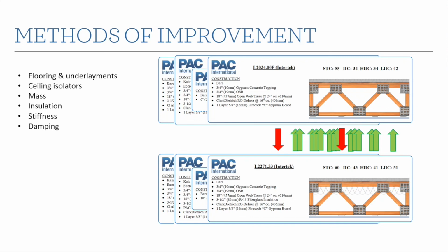Now, something to look out for here is, okay, if a little bit of insulation is good, why not put more insulation in there? Why not fill the entire cavity? That can improve your acoustical performance, although like with a lot of things in acoustics, once you've made one step in including an element and then increase it, like increasing the thickness of your insulation, you get sort of incremental gains in performance, not just a big gain.